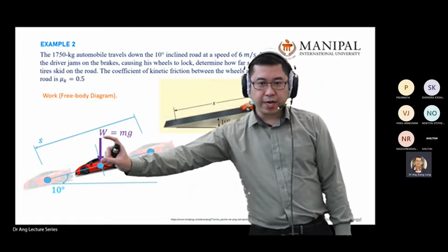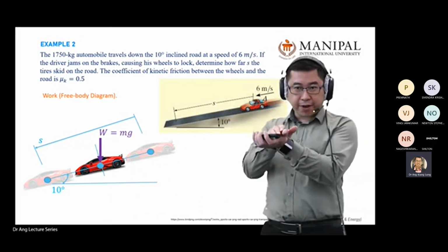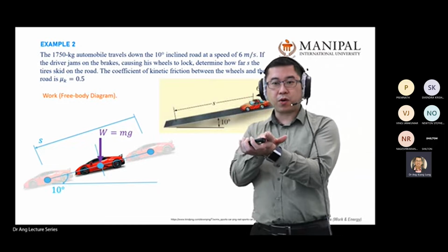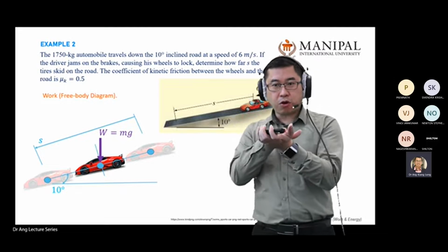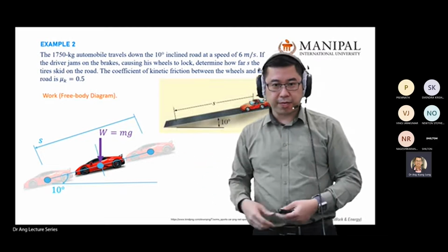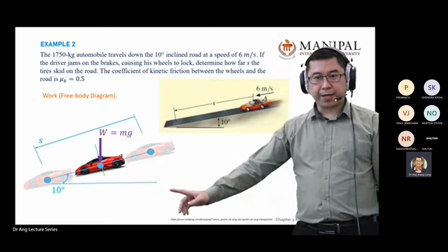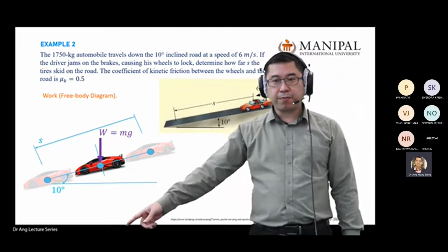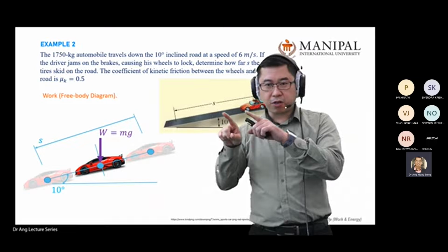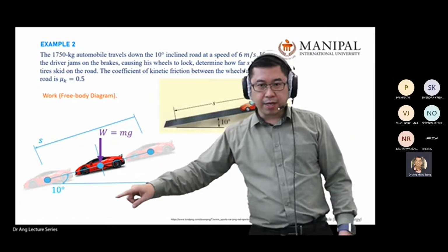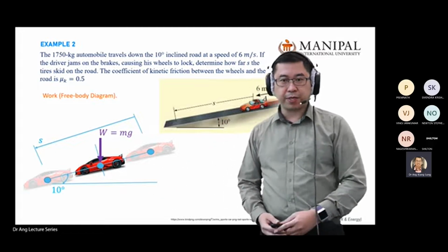But when you have a contact surface, you always need to recall that there is a normal force in the free body diagram. I don't want to overlap my weight here when I prepare the slides. In your exam, you can draw the arrows for the weight and the normal force with some distance, so I know there are two forces in your free body diagram.